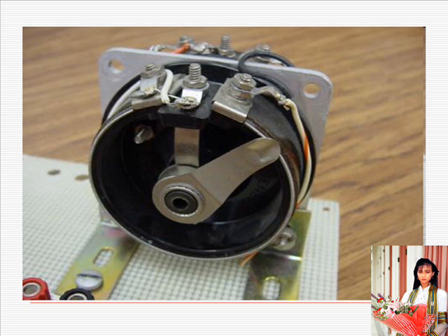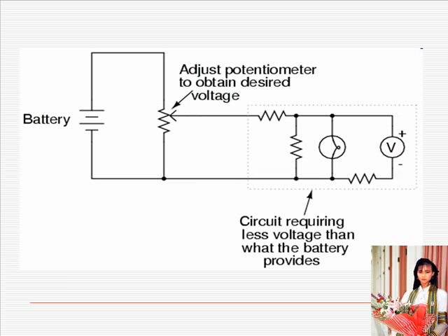If a constant voltage is applied between the outer terminals across the length of the slide wire, the wiper position will tap off a fraction of the applied voltage, measurable between the wiper contact and either of the other two terminals. The fractional value depends entirely on the physical position of the wiper. Just like the fixed voltage divider, the potentiometer's voltage division ratio is strictly a function of resistance and not of the magnitude of applied voltage.